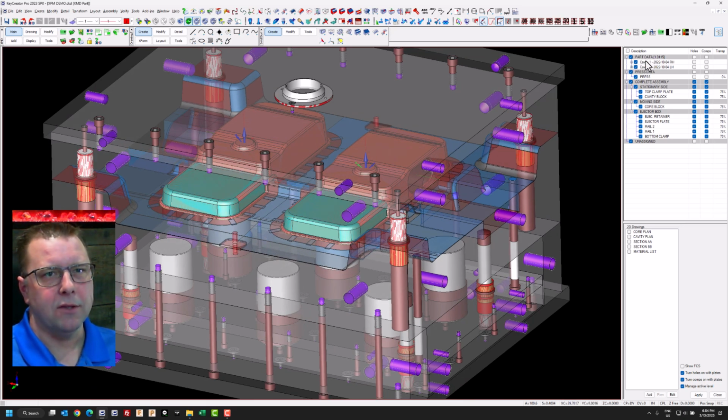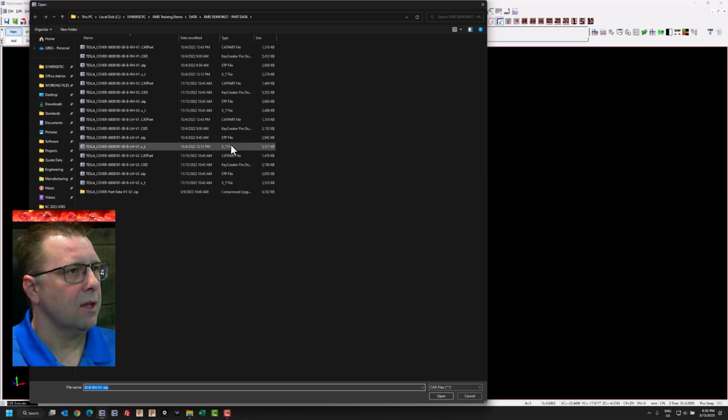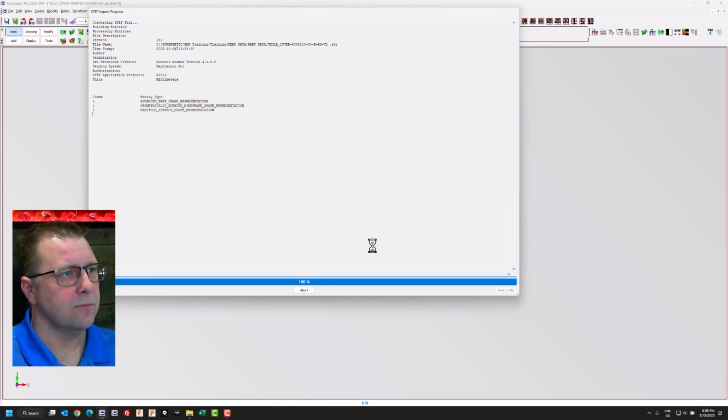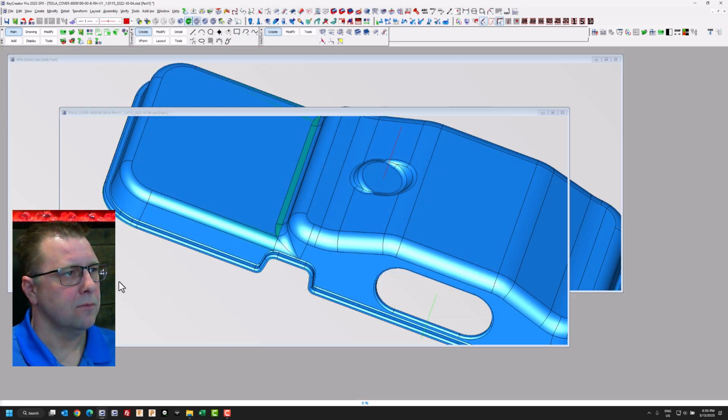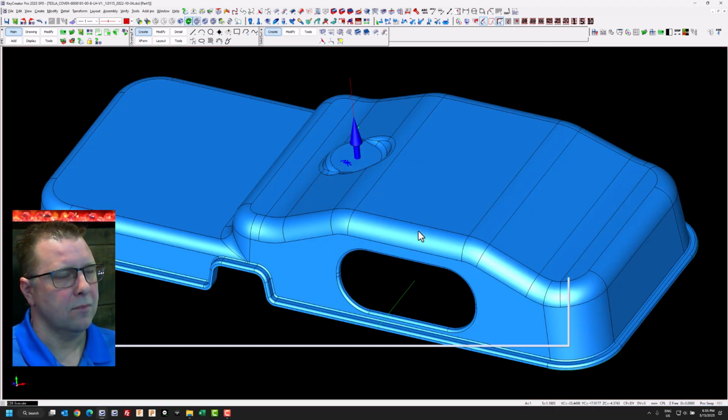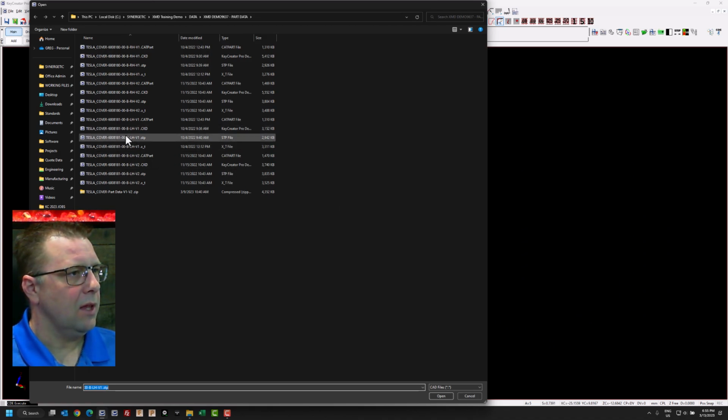You come up and you select in our design navigator, select on the cavities. We're going to swap both parts. Right click, swap part. So we're swapping out the right hand V1 for the right hand V2. And the left hand V1 for the left hand version 2.